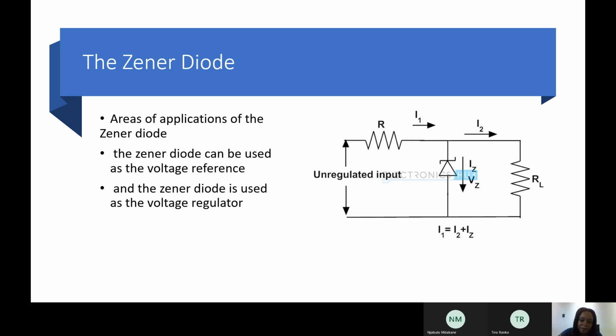It has to be the right value to make sure that the voltage that goes to the Zener diode is exactly the amount the Zener diode needs, or else it can cause the Zener diode to get damaged. So we have to find the maximum power the Zener diode can use so that we can find out the exact value this resistor has to be, so that it can take down any voltage or eliminate any current that could damage the Zener diode. You need to understand that the series resistor causes a voltage drop, protecting the Zener diode. So that's why we work it out.